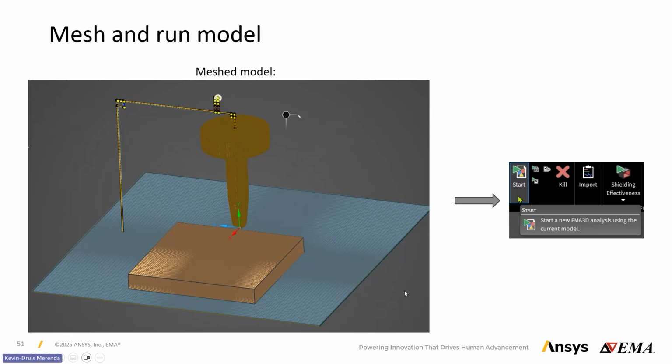So now we're looking at the mesh. You can see this extension of the variable mesh that I was talking about all the way to the edge of the grid. So you can see that on the z-axis and x-axis here, we have the 0.2 millimeter mesh that is extended to the domain boundary. But you can still see that a lot of the problem space is meshed at 2 millimeters, which is key because it would be very time consuming to run all this at 0.2.